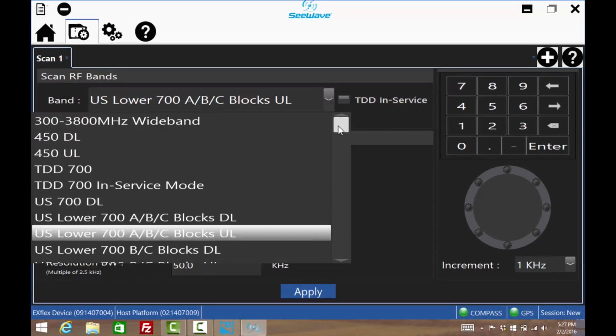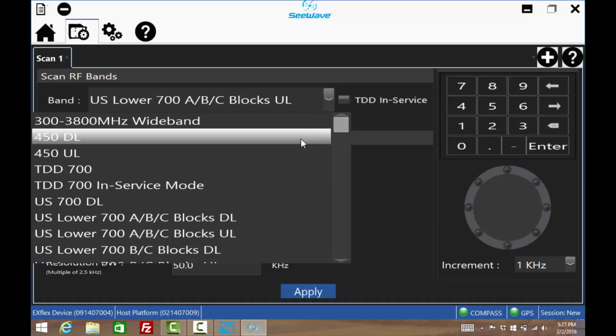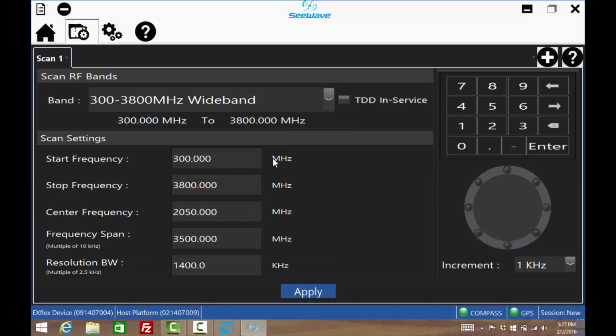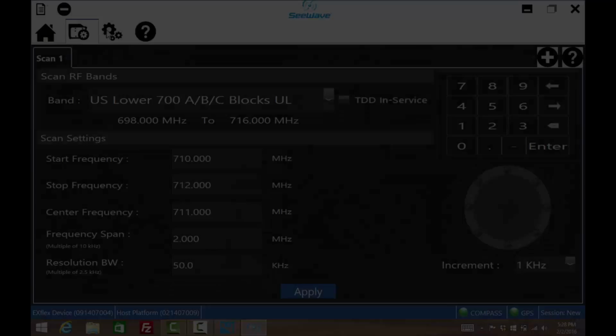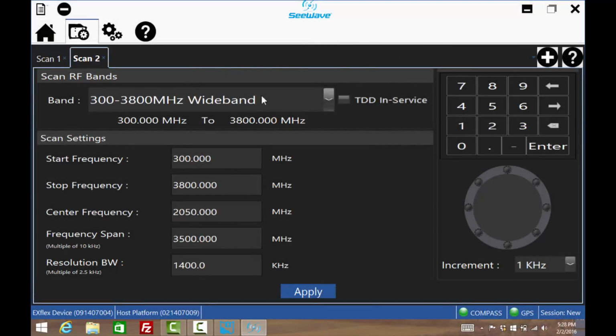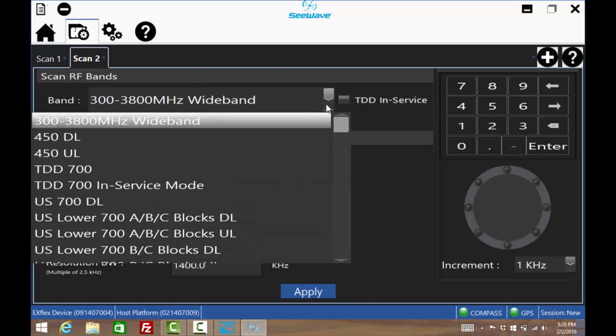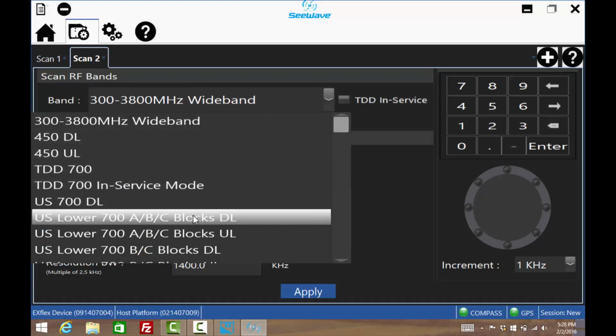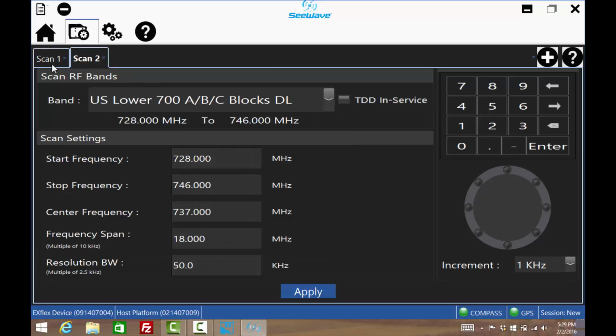For non-mobile phone interference, choose the wideband mode and select the appropriate frequencies. Here, let's select 500 to 510 MHz. 2 scans can be run simultaneously. Press the plus icon here and set the second scan. This is useful to monitor both uplink and downlink of the same band, or maybe 2 different bands if the interference is thought to be really wide.